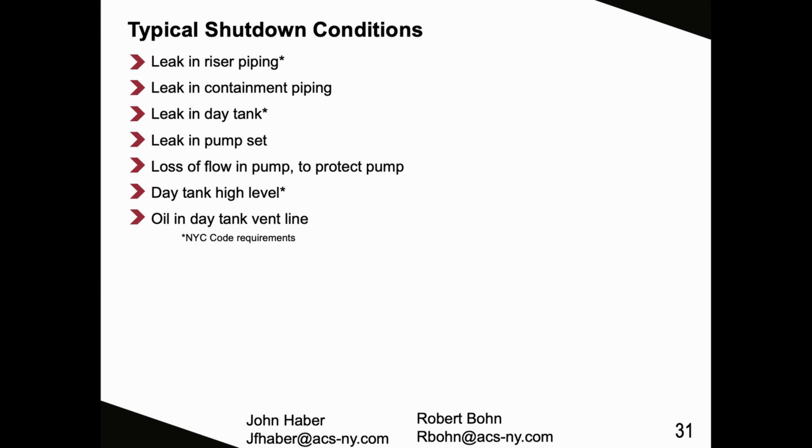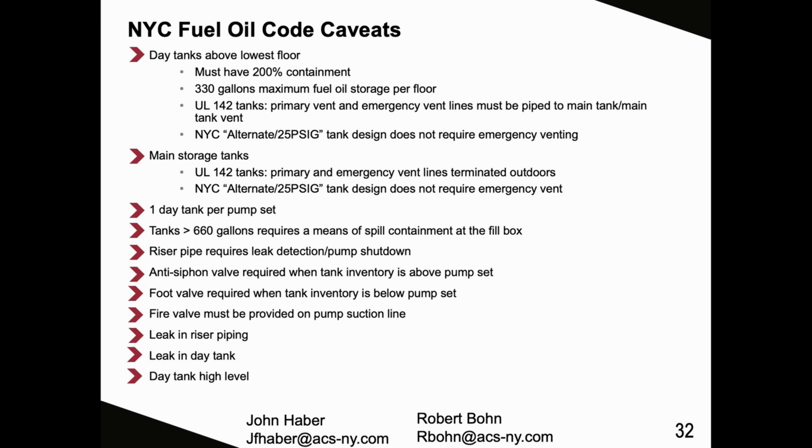These are our typical shutdown conditions that you can see here. The ones with asterisks are New York City code requirements, which are important to pay attention to. New York City fuel oil code caveats. For day tanks above the lowest floor, you must have 200% containment. Your maximum is 330 gallons of storage per floor.